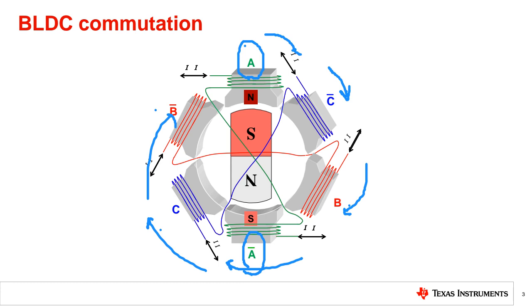Only disadvantage, it needs a complex driver. For example, in your final project, in a DC motor driver, you will use 4 MOSFETs. In a brushless DC motor driver, you will use 6 MOSFETs. Also, you will check currents, voltage, and Hall position.